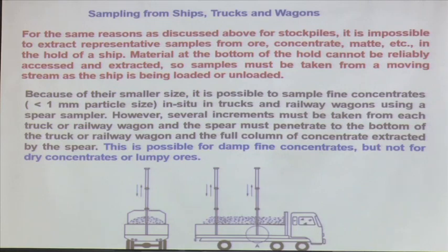Coarsest particle, that is, what is the coarsest particle you have, and then you make sure that you have selected at least 3000 particles. Automatically the other sample sizes will be more, and then you know how many samples you have to collect. Okay? That is a thumb rule, some industrial practice I can say.